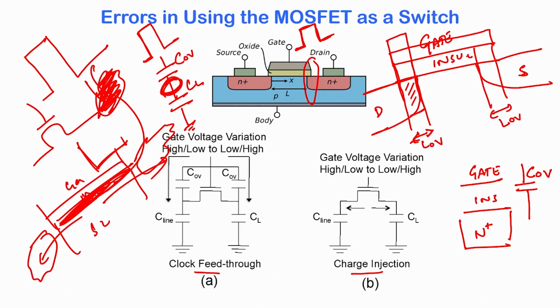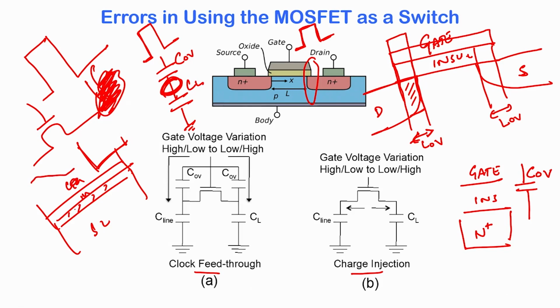Now, if you turn off the gate very slowly and give this charge enough time to realize which is the low impedance path, which means the part which has a larger capacitor, then you will find that most of the charge goes to that part and very little charge goes to the higher impedance path.